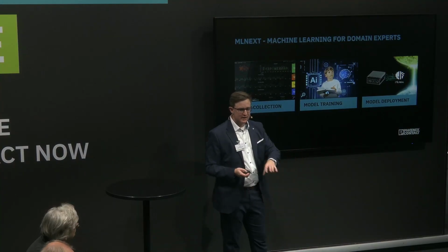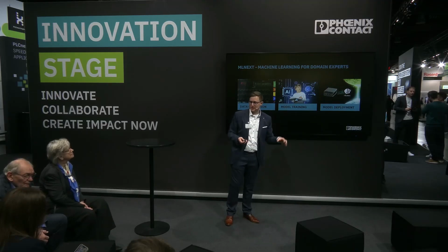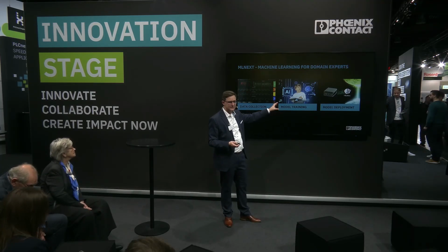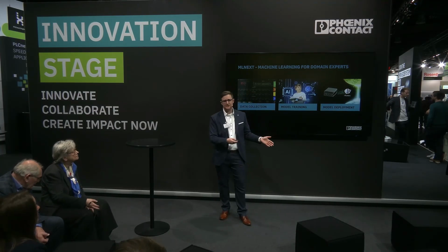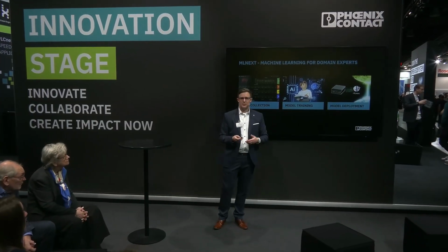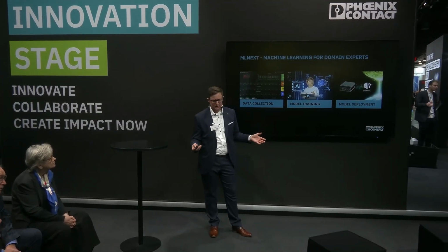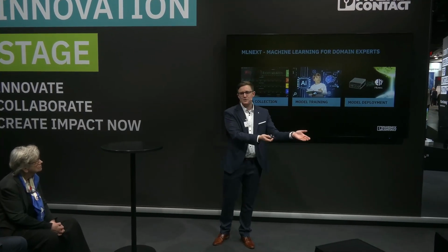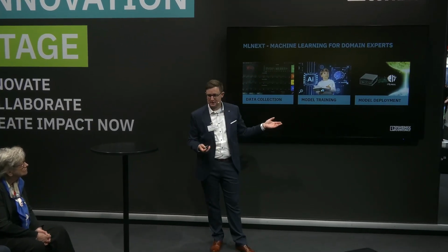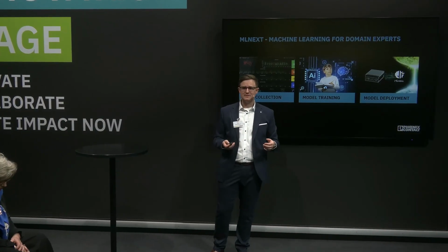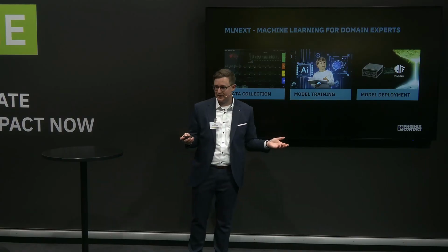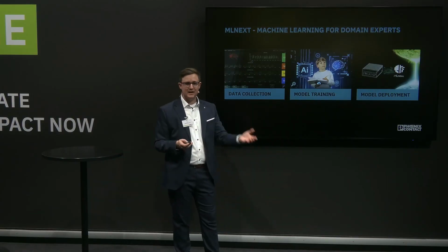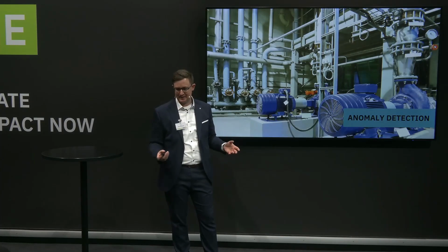And that is why we investigate if it's ideal to implement the machine learning model directly at the PLC or at the edge PC, or later also on the industrial PC, or maybe also at the enterprise level at the customer, so in the IT or in the cloud, based on what is needed. So if we have anomaly detection, we need a maintenance person to do the work anyway. So maybe for an anomaly detection system, it's okay that it runs in the cloud and has a response time of 5 to 10 seconds, because nobody can interact with it faster anyway. So that is what we really have to investigate based on the applications that we currently implement.